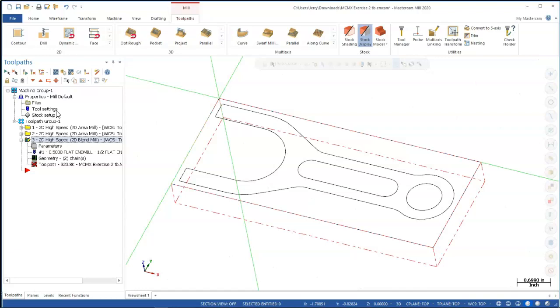And if we're making a couple dozen parts that we can dial it in and bring it closer and closer to tolerance, then probably not going to worry about it. If it's something that is a bore, or we're trying to hold plus or minus a thou or plus or minus a couple tenths, then I'm going to make it a contour so that I can identify just that operation and run it until I get the desired result. So yeah, make those decisions as you go. It's nice having it within the operation, but if it doesn't give me what I want, I'm going to uncheck that box and put in an operation that will.